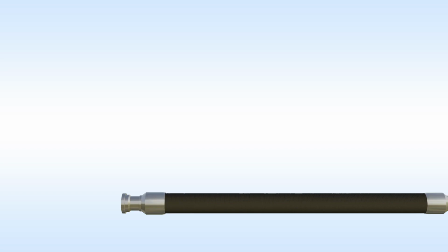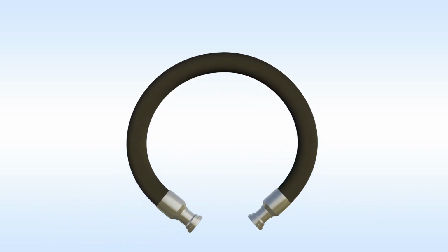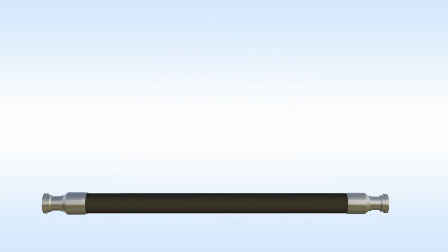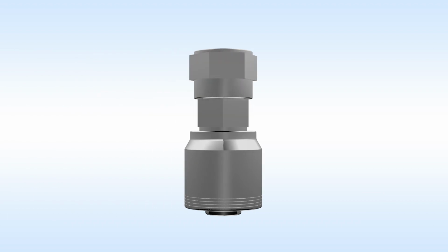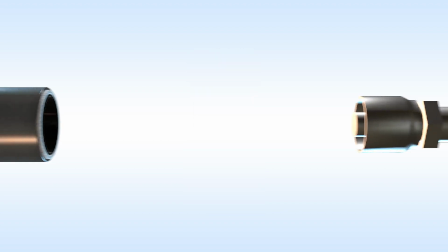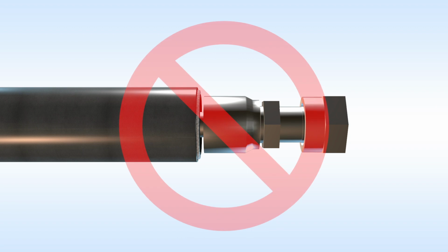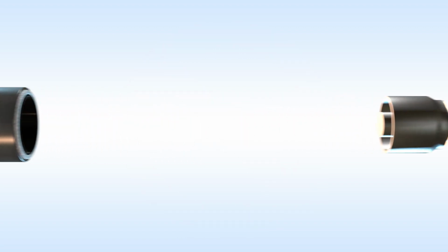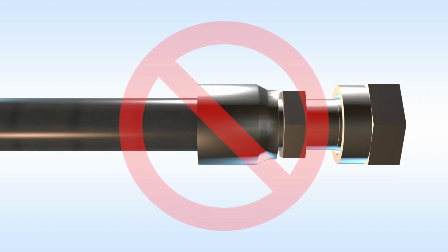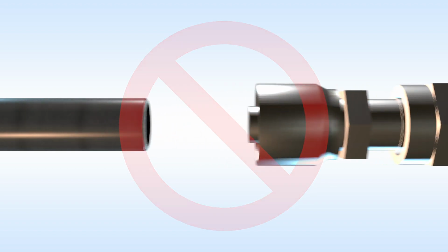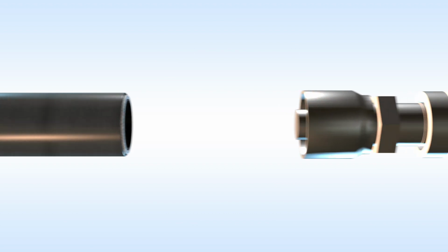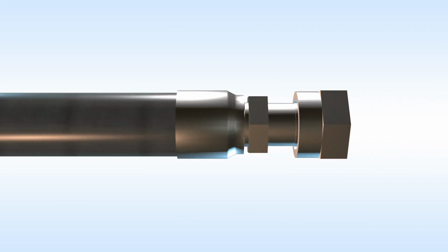Let's discuss the hose assembly. A hose assembly is defined as a flexible hose and its hose ends attached. The hose end is defined as the hose coupling or hose fitting that is attached to each end of a single piece of hose. Hose ends should be properly matched to the hose based on proven type test results. Matched means that the hose dimensions and tolerances are compatible with the dimensions and tolerance of the fittings to ensure that the joint meets the impulse and burst tests for the hose assembly.